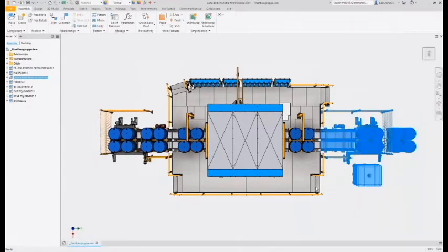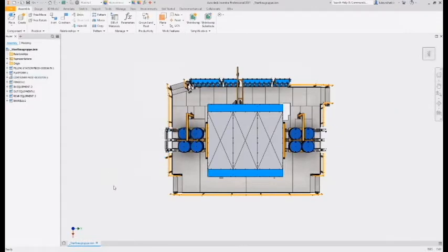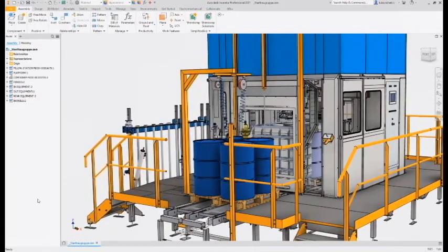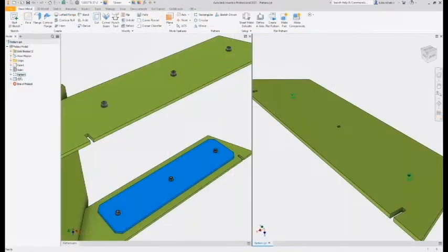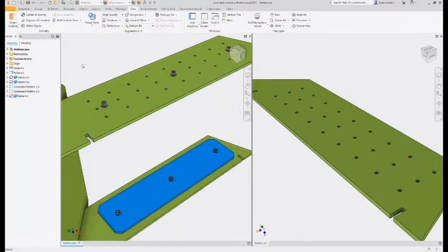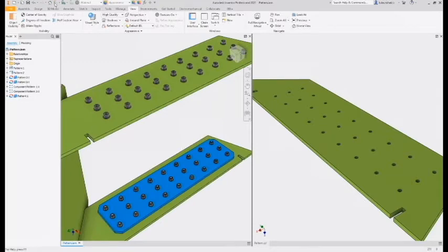The user is bringing in all those different sub-assemblies and just grounding them to basically the origin location. And you can see that once those components get brought in, inserted at the origin, there's very little wait time as far as being able to bring in additional sub-assemblies. And then here they're going to be adding some additional holes in the right view, and then in the left view where those socketed cap screws are, you're going to see that it's going to update pretty quick as far as adding additional socketed cap screws in there.